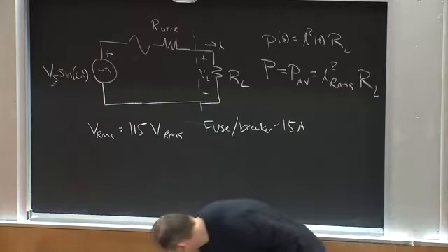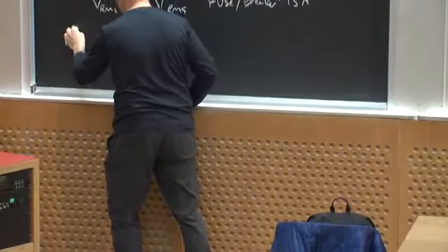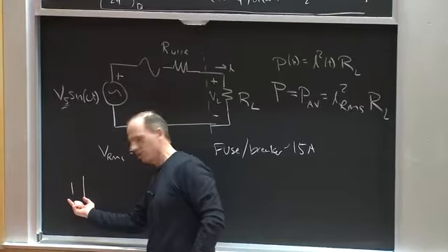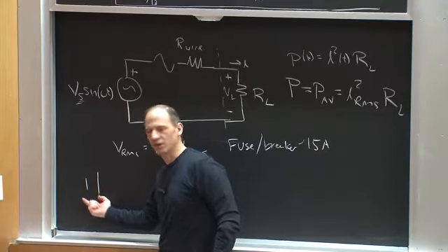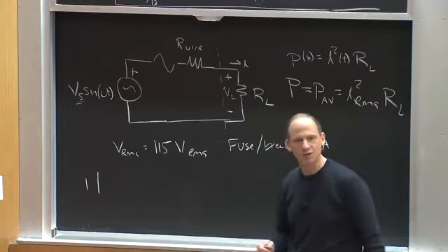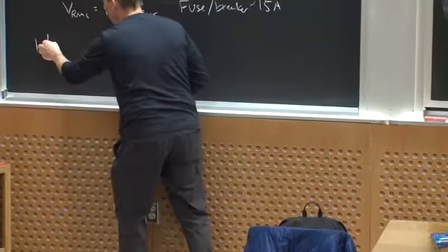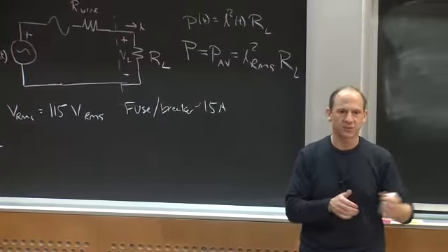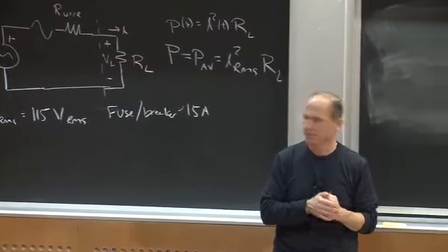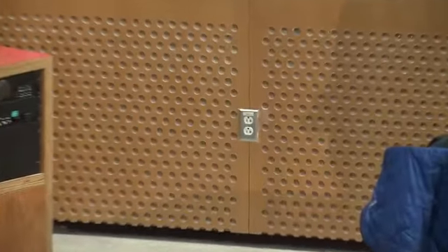Now this plug here, if you have two plugs, a long one and a short one, right? If your plug looks like this, that's a 15 amp circuit. So it's intended that you're plugging that back into a 15 amp line. If you looked at this one in particular, it actually has another sideways pin that you could plug something in up to 20 amps, and you'd have a slightly different plug to do that, right? That means the wall wiring in this case is a little bit heftier and can carry more current, and the breaker's designed to carry that. Okay, so this is by the by.